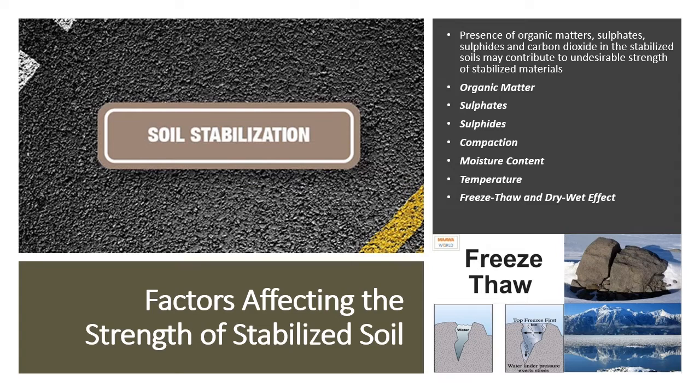In cement stabilization of soil, the hydration process takes place immediately after cement comes into contact with water. This process involves hardening of the soil mix, which means that it is necessary to compact the soil mix as soon as possible. Any delay in compaction may result in hardening of the stabilized soil mass, and therefore extra compaction effort may be required to bring the same effect. That may lead to serious bond breakage and hence loss of strength.